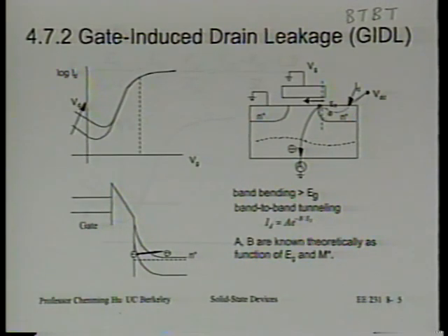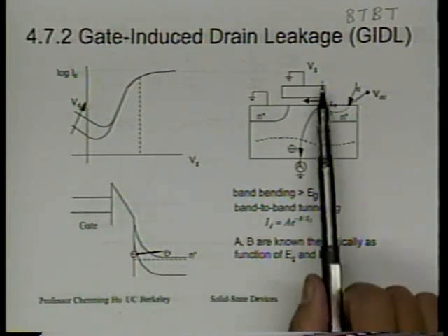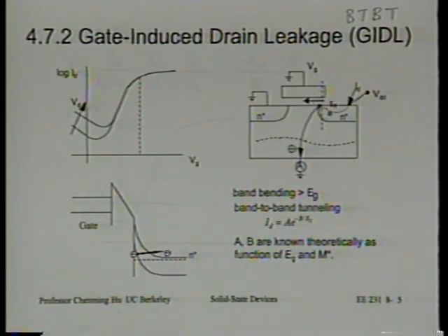Usually, a very important discovery is made just by accident, by noticing the details. So it turns out this was not a leakage in the cable. It's quite reproducible, and once you think about it, it's not too difficult to understand. We understand today that this happens in the region where the drain and the gate overlap, all right?